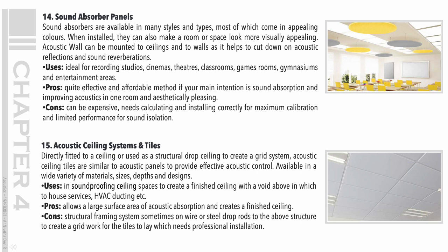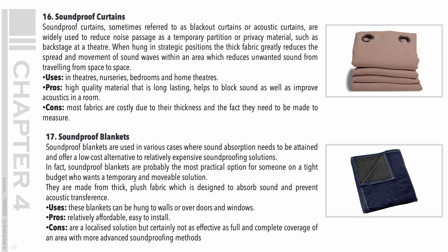15. Acoustic ceiling systems and tiles. Directly fitted to a ceiling or used as a structural drop ceiling to create a grid system, acoustic ceiling tiles are similar to acoustic panels to provide effective acoustic control. Available in a wide variety of materials, sizes, depths and designs. Uses: in soundproofing ceiling spaces to create a finished ceiling with a void above in which to house services, HVAC ducting etc.